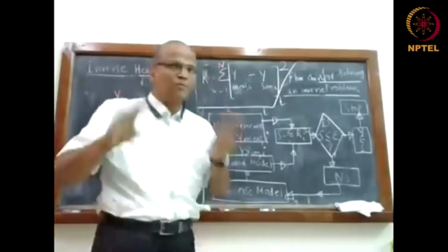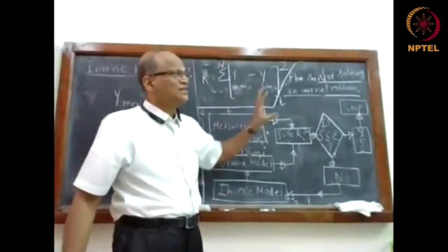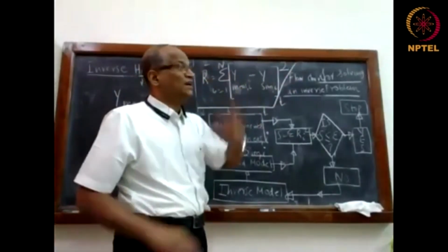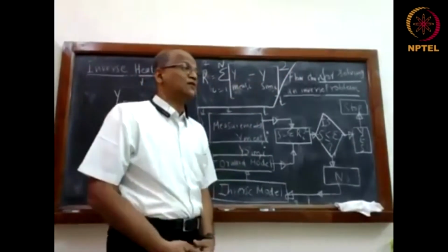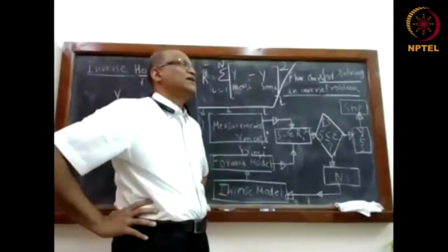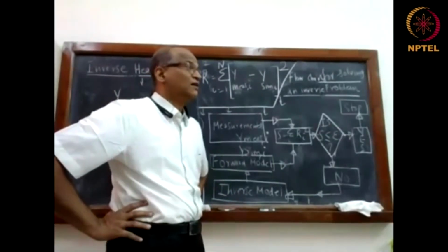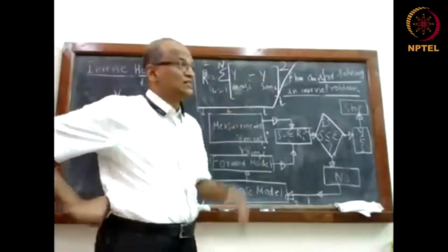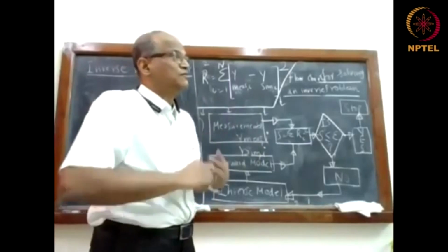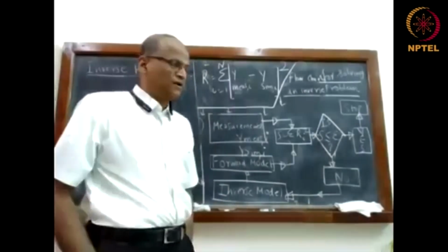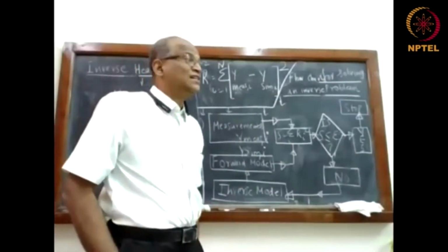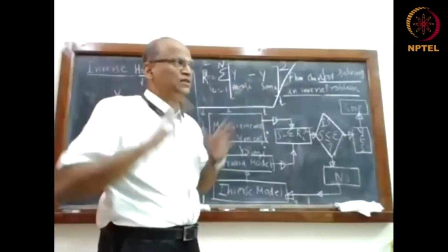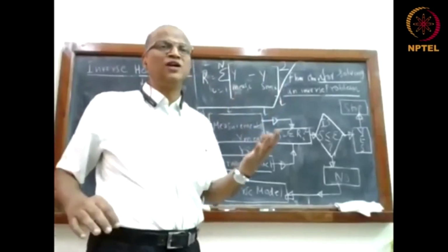Okay. Now, how do we approach? What is this subject? There is a slab. It is giving some measurement. So it comes in heat transfer. Whether it is coming in conduction, convection, or radiation. Okay, it is coming in conduction. Is it steady or unsteady? Looks like it is steady. Is it 1-dimensional, 2-dimensional, 3-dimensional? Yes, it's 1-dimensional. Is it a cylinder, slab, or a sphere? Plain wall. Is there a heat generation? No, there is no heat generation. Okay, now can I write down the governing equation for this? Yes. Now you are cooking with fire.